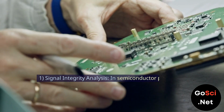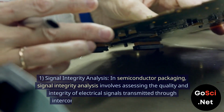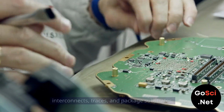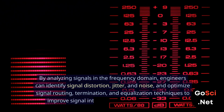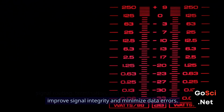1. Signal integrity analysis. In semiconductor packaging, signal integrity analysis involves assessing the quality and integrity of electrical signals transmitted through interconnects, traces, and package substrates. By analyzing signals in the frequency domain, engineers can identify signal distortion, jitter, and noise, and optimize signal routing, termination, and equalization techniques to improve signal integrity and minimize data errors.